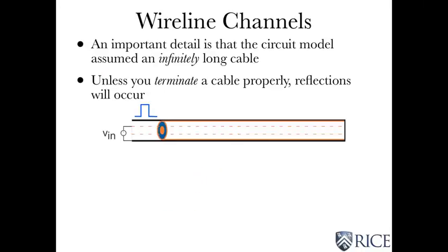Well, this has very important consequences in actually building wireline channels. Now there's a detail that I should have emphasized but didn't: the circuit model and the KCL and KVL equations we use to derive them assume the cable is very, very long. In other words, that KCL equation is applied at every point in space. That was very important.